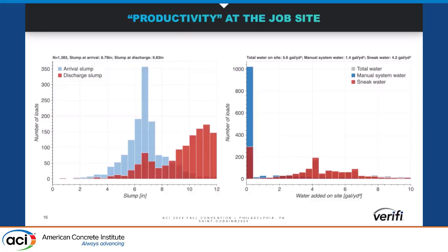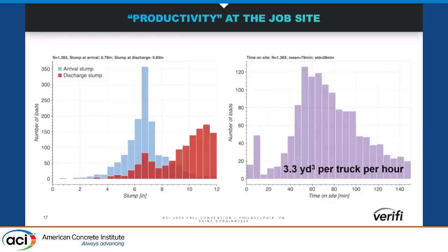So now if we take a step forward and talk about that 10 minutes of extra time, this is actually the total time on site. So from basically you arrive to the site and then when you're done discharging. This doesn't count any time that they're just screwing around on the site afterwards. This is once you've dumped your concrete, this is the time that you're on there. So you're going all the way up to 140 minutes. Average cycle time that Tarek was talking about, that's about 100 minutes. It's kind of strange, it's almost 100 minutes no matter where you go.